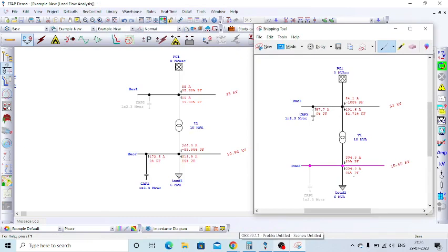Can you see the difference in the low voltage side? When we connected the 3.3 mvar capacitor bank in the high voltage bus, the load remained at 85 percentage, and the transformer circuit was also 85 percentage. So it resulted in 304.9 ampere in the LV side.